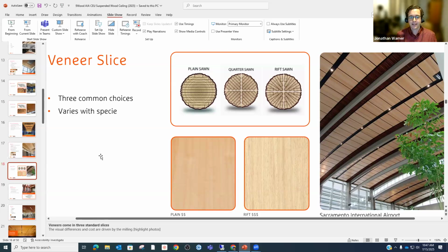And so ideally, to avoid that, you acclimatize the building before the wood is installed. Ideally, you deliver the wood panels and material planks into the space and let it acclimatize. It usually takes 2 to 4 days, depending on where it's coming from and where it is. And there are ways a manufacturer can actually set up the sub to do that. They can measure the moisture content of the wood and make sure it's reached equilibrium, where it's now in sync with the environment. And then that's the best time to install it.